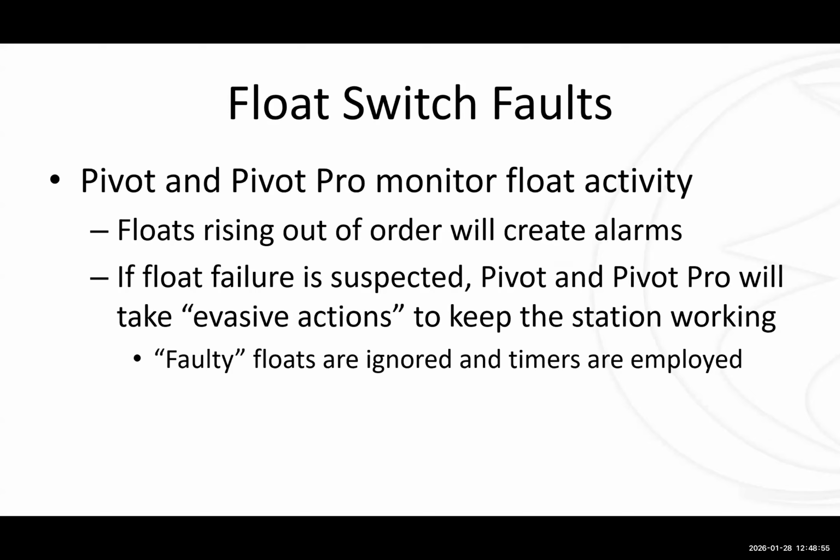They just, over time, either have a tendency to get debris building up on them, or maybe during installation the tether links aren't set appropriately and they get stuck, or over time they fail and they fail to switch appropriately and give an appropriate signal. It's just something that happens, or they get installed out of order. So there are a number of things that can happen with float switches that cause problems with control panels. And we've just seen it for decades.